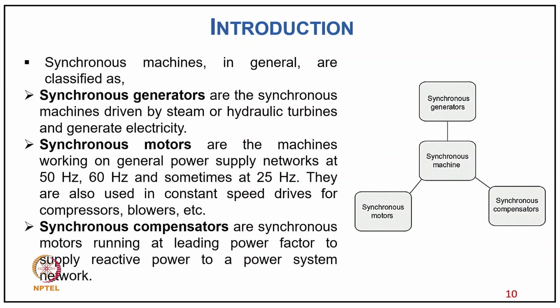So as you look into the diagram, the synchronous machine is normally used as a synchronous generator. Normally 90% of conventional fossil fuel based generators, like nuclear or thermal power stations, are all large turbo generators of round pole type, and of course the small low speed, large rating water wheel generators, normally called hydro generators, are of salient pole construction.